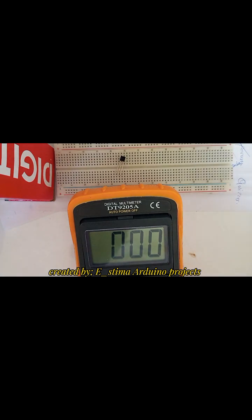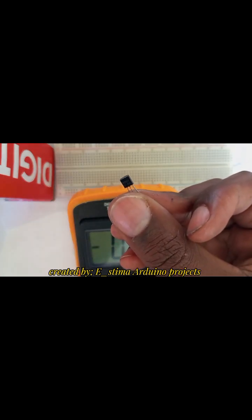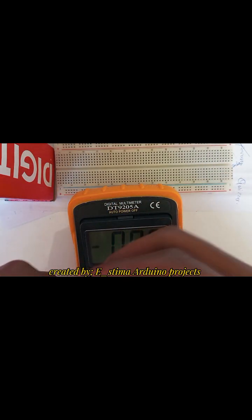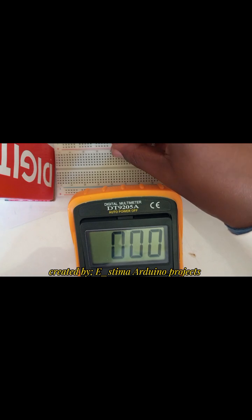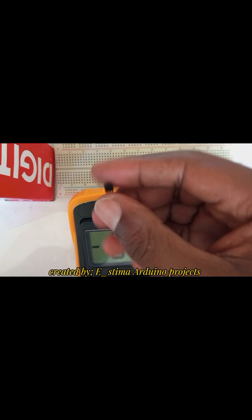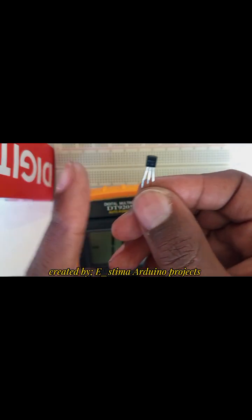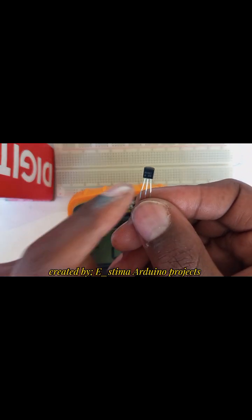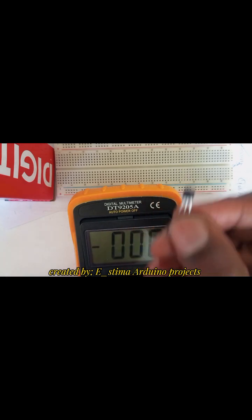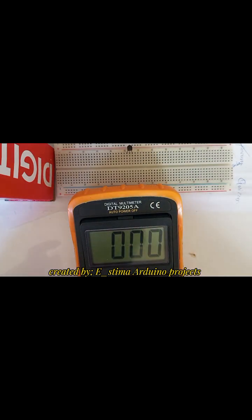Our next transistor is BC557. It is still under bipolar junction transistors. I'm going to fix it on my breadboard like that. Remember, when the flat side is facing you, the farthest pin to your left is pin number 1, the center one number 2, and the far right number 3. So let me fix it on my breadboard like that.